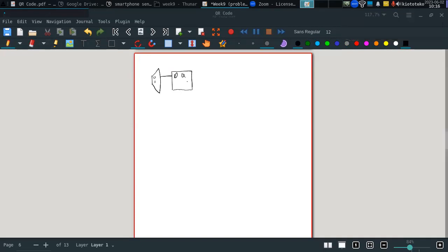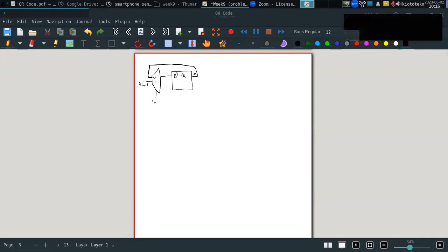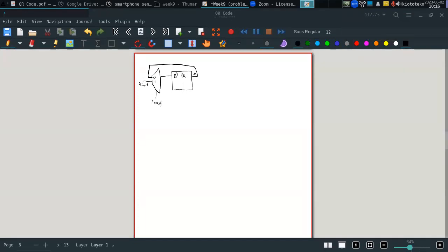We connect this because the value of X will be loaded here, or the value of X will be maintained. Let's put here X in. This is the initial value of X. And you could say this is X. This multiplexer will be controlled by a signal that let's call it load. So this is our signal load.